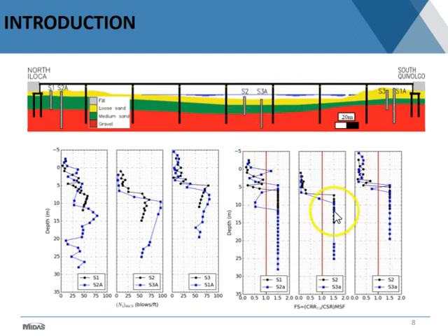This is what you see in terms of factor of safety against liquefaction. Here in the 3 figures on the right, here is the factor of safety of 1, marked with the red vertical line, and of course everything to the left of that line is anticipated to liquefy in this condition. Here you have liquefaction down to a depth of, let's say, 9 meters or something like that, depending on the boring. But in this case, liquefaction is concentrated in the upper material, and the material below a certain depth is not susceptible to liquefaction.